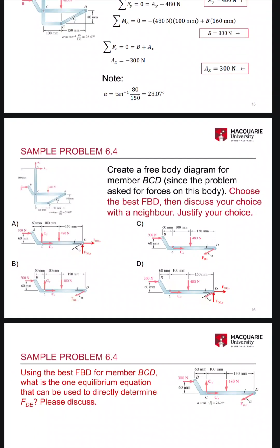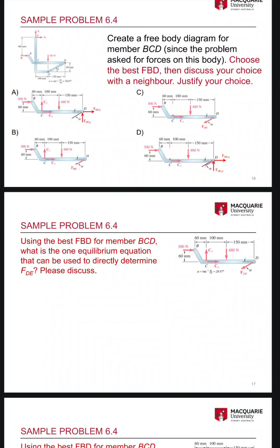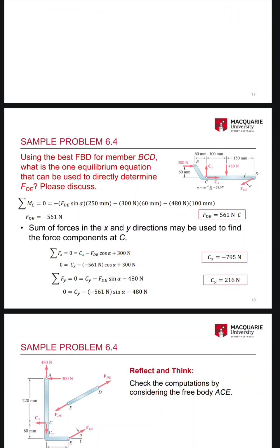And create a free body diagram for member BCD. Since the problem asked for forces on this body, choose the best FBD, then discuss your choice with a neighbor. Justify your choice. A, B, C, D. Using the best FBD for member BCD, what is the one equilibrium equation that can be used to directly determine FDE? Please discuss.